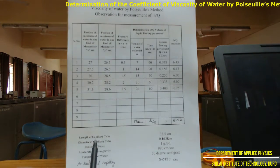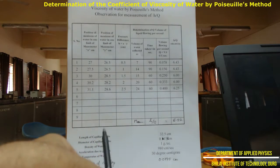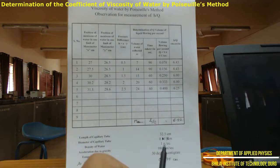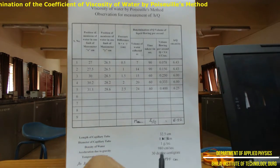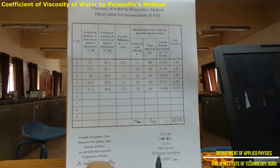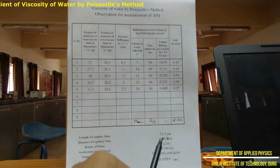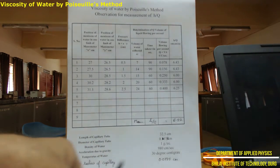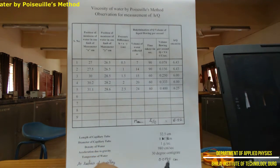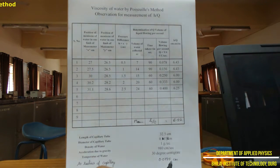Now the length of the capillary which is given is 32.5 centimeter. Diameter of the capillary tube is 0.159 centimeter. Density of water is 1 gram per cc. Acceleration due to gravity is standard, that is 980 centimeter per second squared. Temperature of water was 30 degrees centigrade. If the diameter is 0.159 centimeter, the radius will be 0.159 divided by 2, that is 0.0795 centimeter. So this is all about the readings which we have taken. Now we are going to have the graph and the calculation.